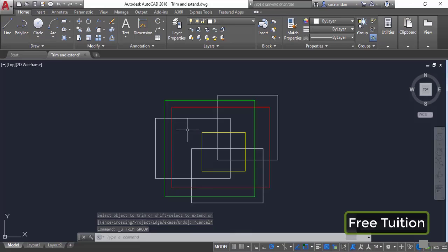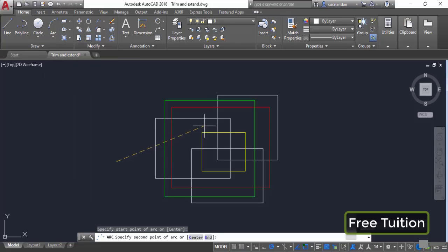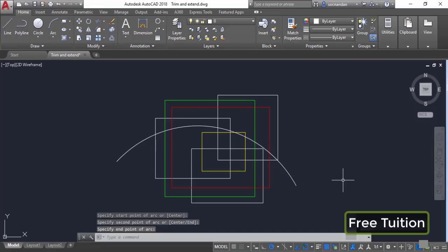In the trim tool, you can trim any object as long as there is a boundary. So if you create an object, let's say that we create this 3-point arc somewhere inside this object here, just like this, and we want to trim this object. So this will only be trimmed if a next boundary is found. So let's select the trim tool, press enter, and now I'll click somewhere inside this geometry and I'll click this part and the part has been removed. Now let's click on this part and let's click on this part. Now if you click on this part, it won't be trimmed because there is no boundary after that. So we have this one as the last boundary. After that, we don't have any boundary.